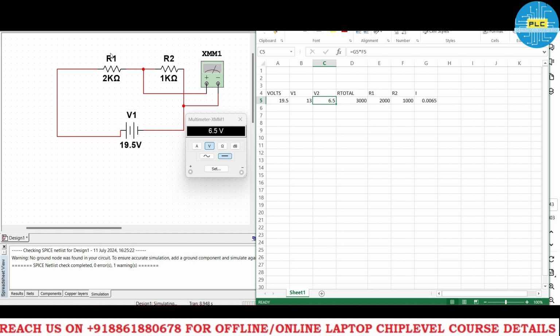In case R1 is greater than R2, now Vin is 13 volts and the voltage across R2 is 6.5 volts. It means in case R2 is lesser than R1, then you will get lesser voltage across this voltage divider.